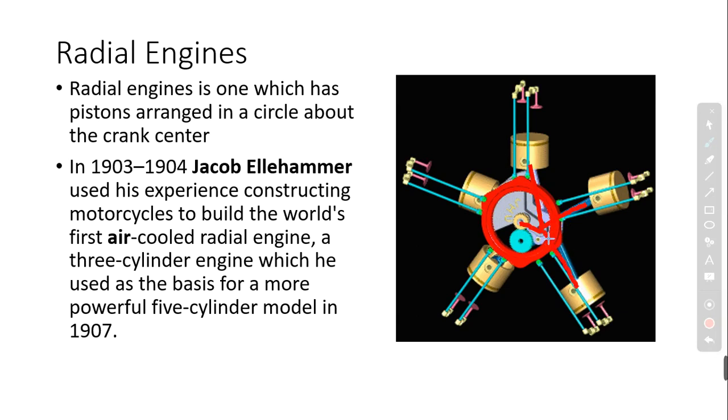There is only a single crank for all the pistons, and this is the connecting rod. Only the line of stroke of this engine is arranged in an angular manner. Don't confuse that all the pistons have different cranks. There is only one crank, and the line of stroke is different for different cylinders.